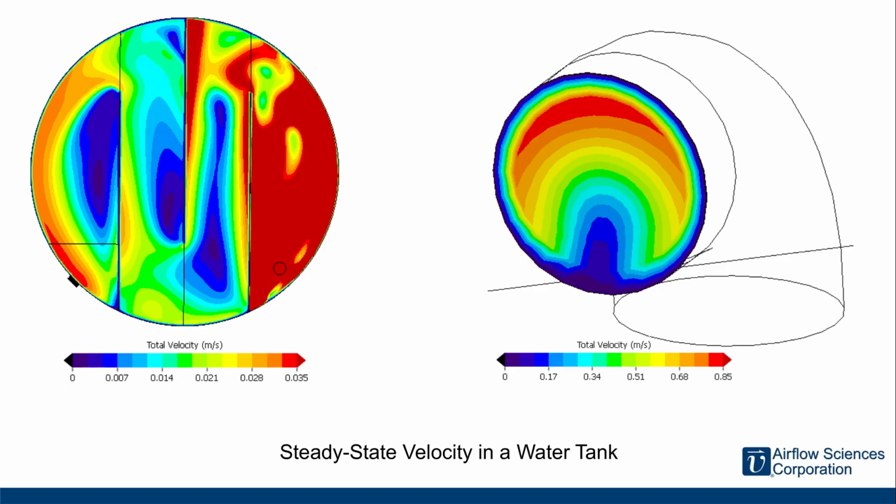The baffling factor is a way of characterizing the effectiveness of flow through a given tank by quantifying the mixing of the chemicals. By finding the time for the tracer concentration to reach 10% of the total flow of the tank exit and comparing it to the theoretical time for the entire fluid volume to fill the tank, the baffling factor can be calculated as a simple ratio. This baffling factor can range from 0 to 1, with higher values corresponding to better mixing.